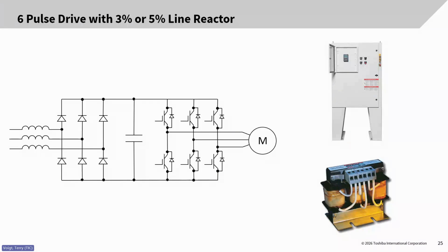That helps with reducing harmonics, similarly to a DC link reactor, but it also has the advantage of incoming transient protection. Any voltage spikes or voltage imbalances, the line reactor does a better job of protecting the drive than just a DC link reactor. The harmonic spectrum, depending on the sizing, is a lot of times very similar though. But this can be added after the fact, where a DC link reactor a lot of times can't.